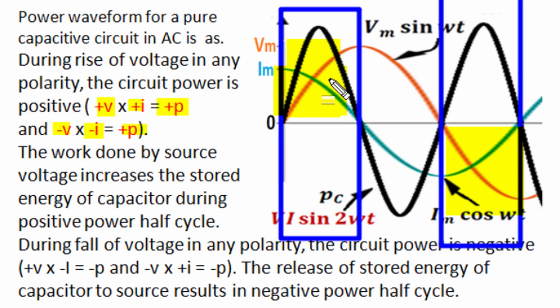So the capacitor with one polarity is increasing polarization in the dielectric substance and storing energy, and at that time the source supplies positive power to the capacitor, and in this quarter the source again supplies power to the capacitor, and the capacitor with opposite polarity stores energy by increase of polarization in the dielectric, whereas in these other two quarter sections, when voltage is decreasing in positive direction, current is discharge current, and when voltage is decreasing in negative polarity, current is charging current, and one out of instantaneous voltage and current is positive, the other is negative, and the product of the two is negative power, and during this negative power, the capacitor releases electrostatic stored energy from the polarized state of the dielectric to the external circuit, and power flow for that release of stored energy becomes negative for the capacitor as shown here in this yellow highlight.